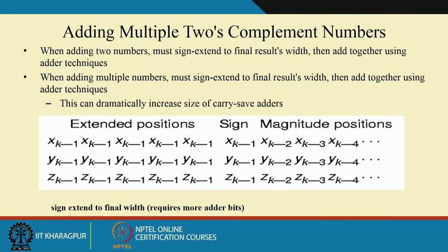Whenever we do the shifting, we are increasing the length on the MSB side from partial product 1. In unsigned multiplication we do not have to bother about the sign of partial product 1, but in signed multiplication we have to.